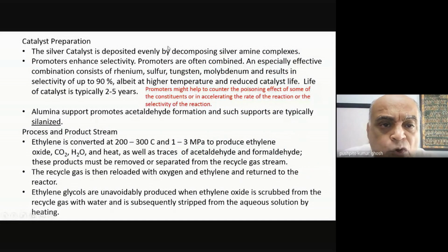Now, here I'm not going to go through it, but the silver catalyst is actually obtained by decomposing a silver amine complex. That's how they get it. And that's why you need to ensure that you don't have any porosity in your support, because the silver amine complex might get inside the pores, and then it forms the islands over there, and then you find that the ethylene oxide is not coming out from the pores that readily. So that's always a problem. You can also see that it's such a complex reaction, but even then the catalyst life is something like 2 to 5 years. It's really good.